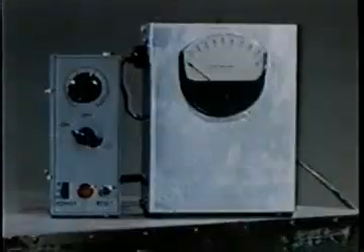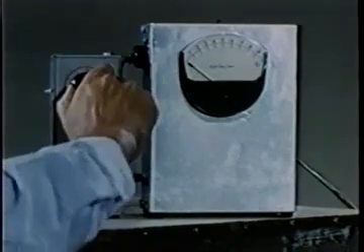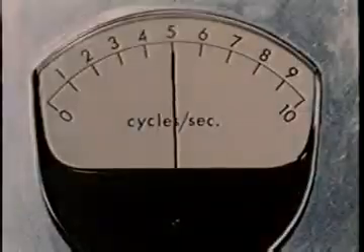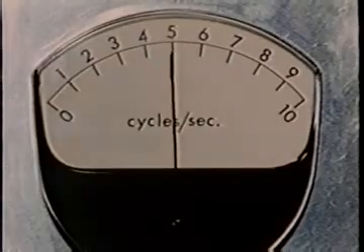In order to find the frequency response of amplification, we put in sinusoidal disturbances which we can control. We start the wave maker oscillating at 5 cycles per second. At 0 airspeed, the waves damp as they travel away from the wave maker. With the tunnel running, but below critical airspeed, we don't notice much change in wave damping. As we increase the airspeed and pass critical speed, we see the waves grow.